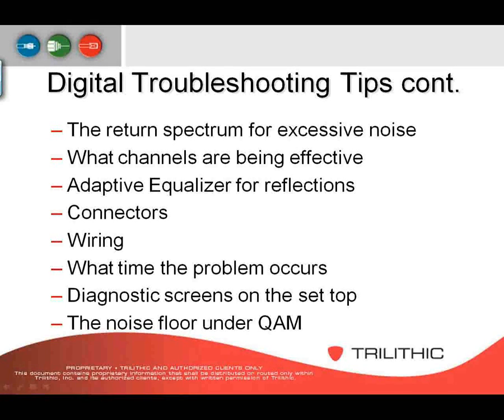Check your connectors, making sure they're nice and snug, because that's one of the biggest problems that I run into when I'm looking in the plant: loose connectors, and that will cause you a lot of problems. Make sure the wiring is proper, and then verify what time the problems actually occur.